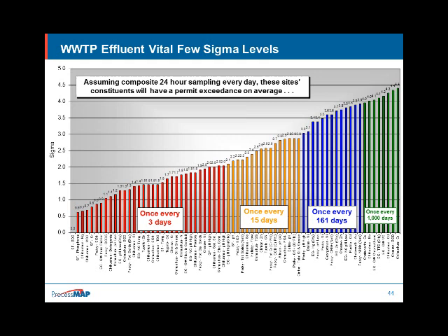I can tell people that, hey, we don't have good capability, but seeing it in this way, seeing it real, really changes things. We talked about 4.5 sigma being out of compliance every 3 years, right? 6 sigma, I was working with one company that for every new pollution prevention device that they put in, they wanted it to have 10 sigma capability. If you'd imagine 10 sigma capability, that's running for like over 1,000 years, right? Continuous monitoring, never going out of compliance. Talk about being able to sleep at night as an EHS person responsible for compliance. Knowing this kind of information is vital, vital, vital in the roles that we do. And I'm just shocked that this isn't really taught in too many places, and this is really, really a shame.